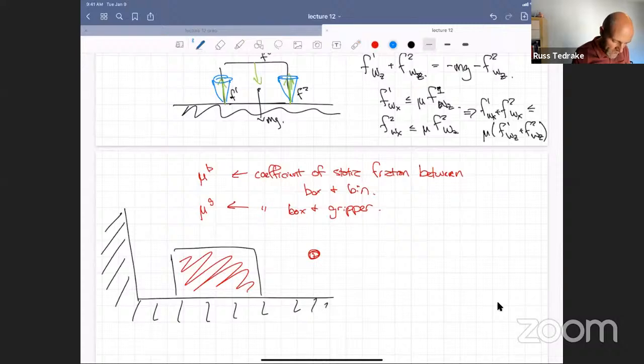What happens if I apply just a constant force on my fingertip directly to the right? Well, I could tell you what happens because I did that first and I forgot, and I was like, why is my finger ending up down here? And then I realized I have to add gravity plus a constant force. But it's the simplest controller you can imagine: cancel out gravity and then add a constant force. And let's just say hold it on for 1 second. What happens to the system?